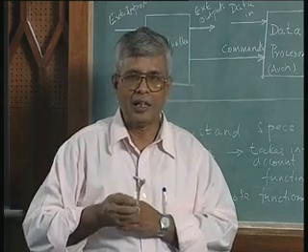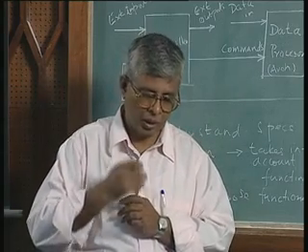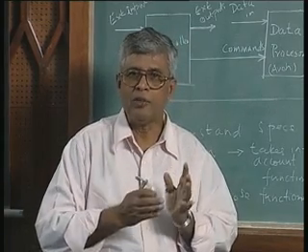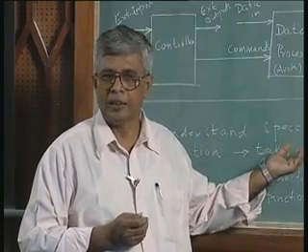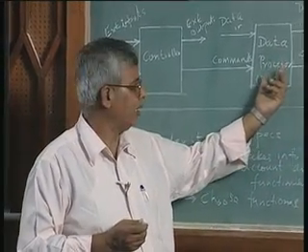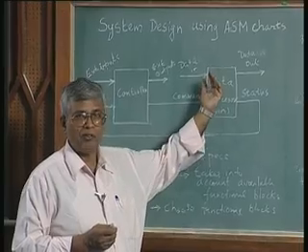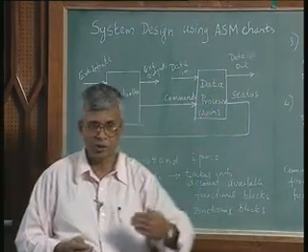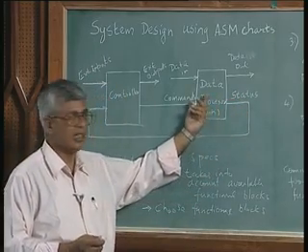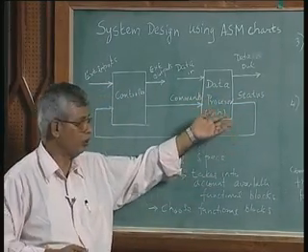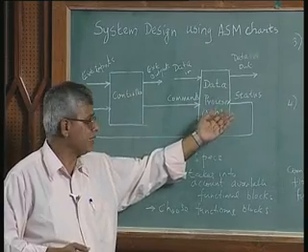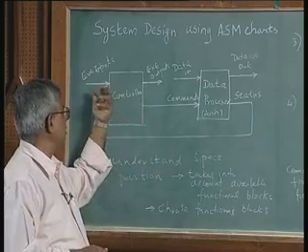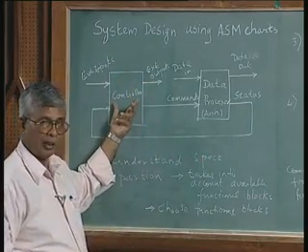In an older concept we used to call it off the shelf components, that is the same thing. The concept is the same whether it is an IC design or a discrete design. So you identify the processor functional blocks, clearly find out whether they are capable of delivering the goods in terms of the data processing that is required, that is the ultimate goal of course, but identify the command signals required to initiate or activate each of those functional blocks, and identify the status signals that each of these functional blocks will give at different stages. Take those into account along with the external inputs and outputs to design your controller.